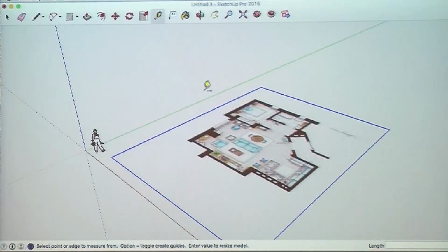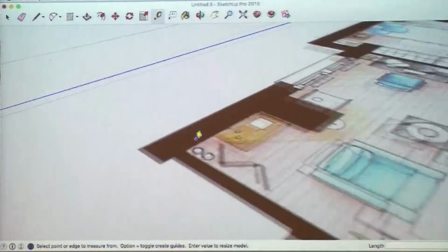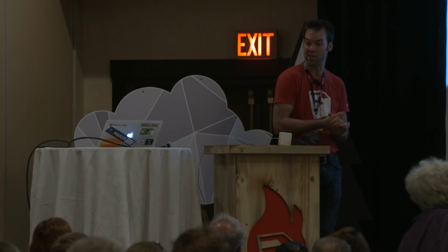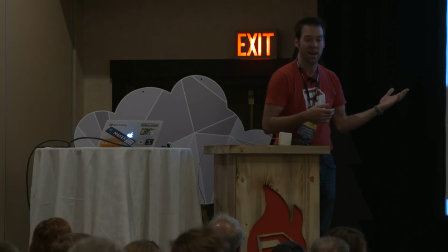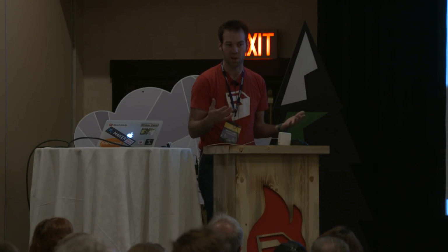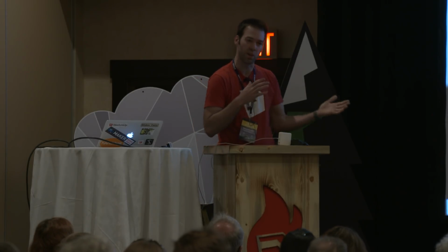So a tip for doing this, and did you guys notice when I zoomed in here that this is kind of pixelated? So it's a little fuzzy about exactly where you're getting it. At this point in the design process, I'm usually working off of a PDF or theoretical dimensions. This is fine. It's going to get you really close. And typically what I do is go back after something is rough framed. We'll get real field dimensions and then go back and adjust your model. So we're really at the design and proposal stage right now.